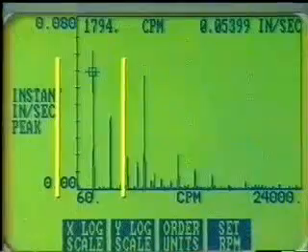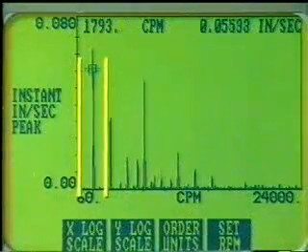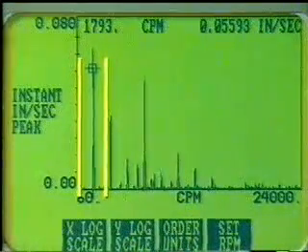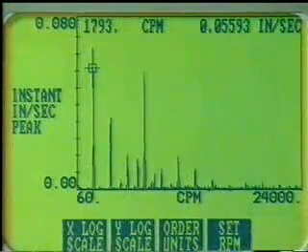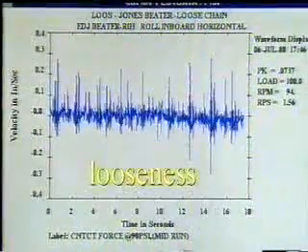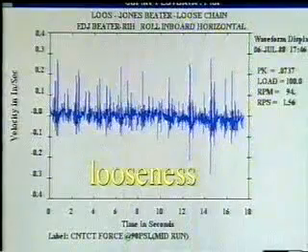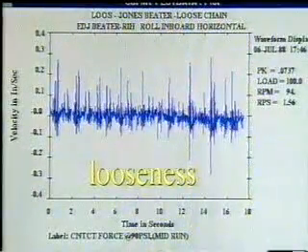Erratic or unstable phase measurements can be associated with rotating element looseness. During normal phase measurements, if the phase is very unsteady, not simply slowly rotating or staying within a certain window, then check the spectrum for peaks near the 1 times peak and verify that the bandwidth is narrow enough to include only the 1 times peak. Also check for a looseness spectral pattern, that is, multiple harmonics of the turning speed peak. The waveform of a looseness condition will have a very non-repetitive pattern due to the random impacts as the rotor is rattling around in the mountings.